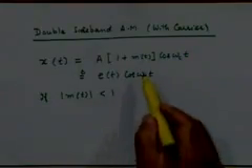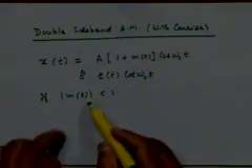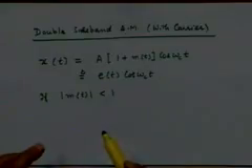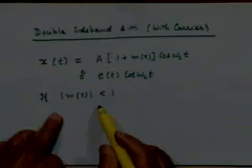So what I am doing is scaling the message waveform in such a manner that its instantaneous amplitude never exceeds 1. It always lies between minus 1 and plus 1. Every message will have some limits in which it lies, right? Every waveform will have some limits in which it lies. I can scale it up or down so that this condition is satisfied, right?